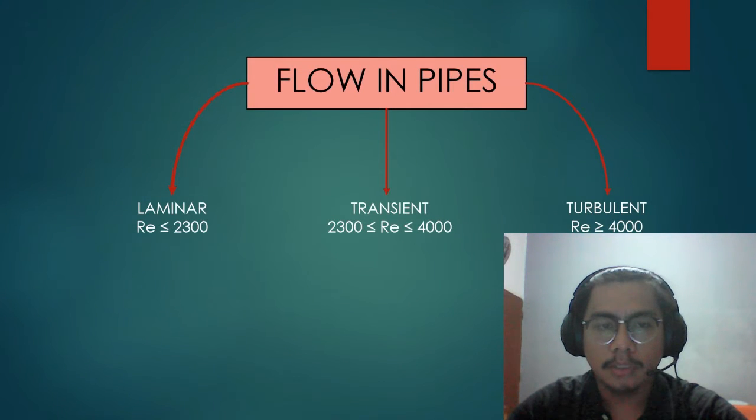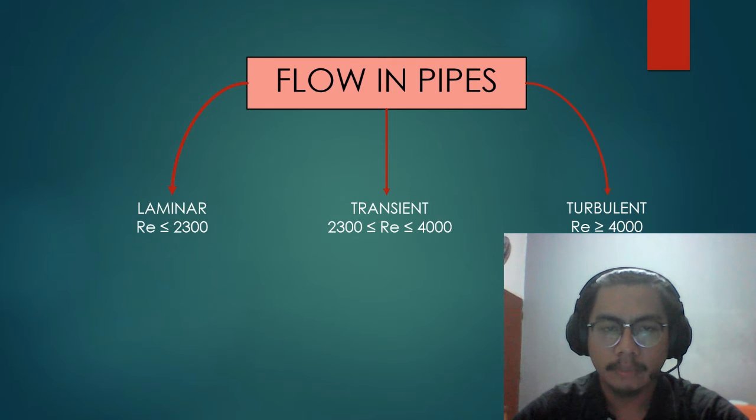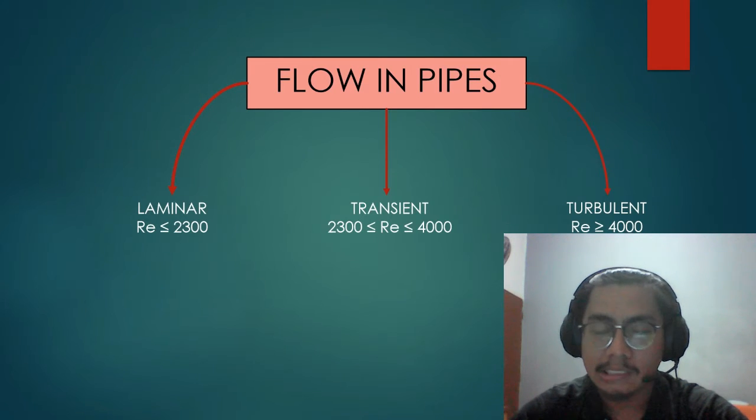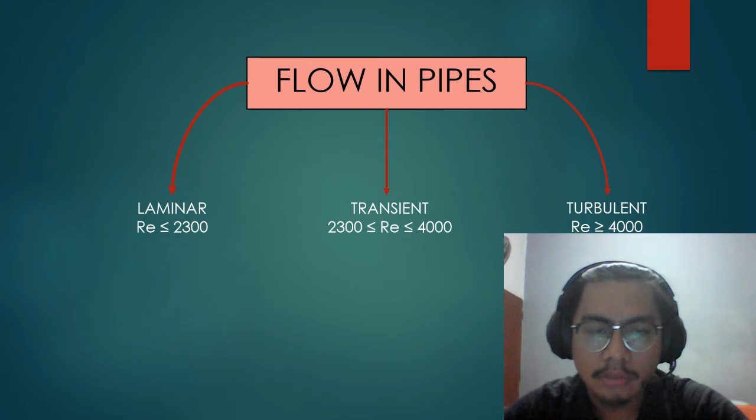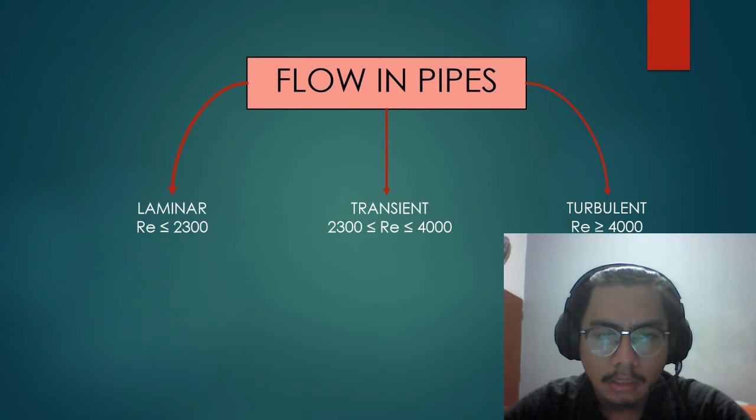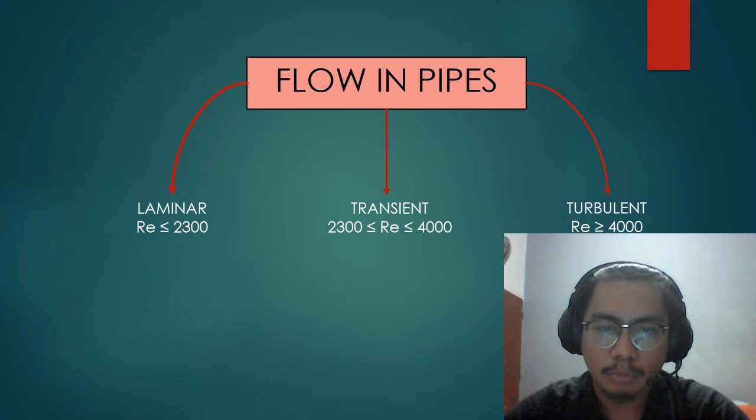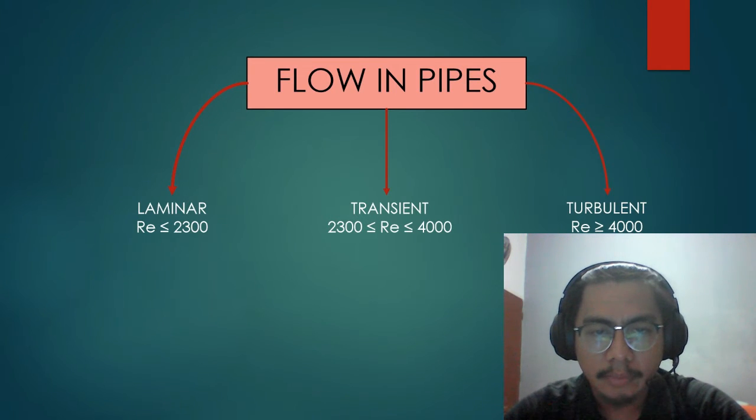For turbulent flow, the turbulent flow is a complex mechanism governed by variability, which is still not completely known. Considering the enormous amount of research in this field, turbulent flow is characterized by uneven and sudden changes in swirling fluid areas, known as eddies, that has Reynolds number more than 4000. These fluctuations provide an additional mechanism for momentum and energy transfer. In turbulent flow, the swirl eddies carry mass, momentum, and energy much faster than molecular diffusion into other flow areas, increasing mass, momentum, and heat transfer considerably.